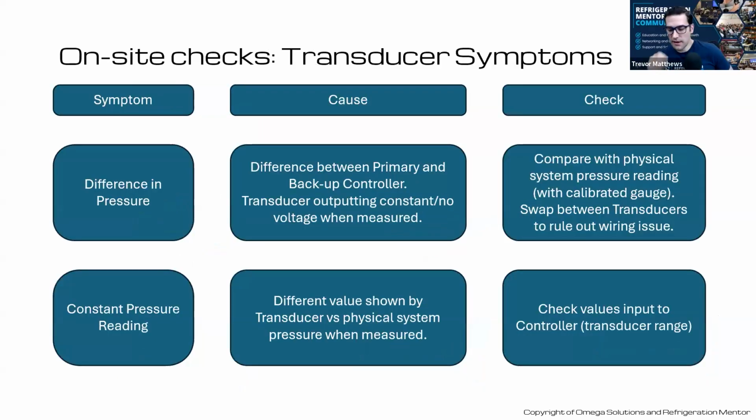I've seen it too. I had a student in my CO2 intro course maybe a month ago. Last class, he was saying that he was at a site and the vessel, the flash tank, the transducer was reading 800 psi, so upwards of 50 bar, I guess. And really in the tank, the pressure relief wasn't going off. He was like, what is going on? So the system shut down, but the pressure relief was like, it was that much pressure in there.